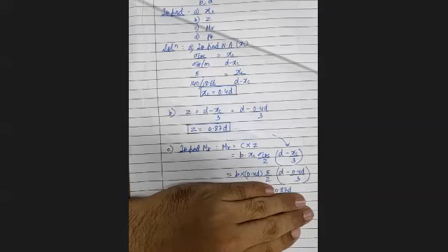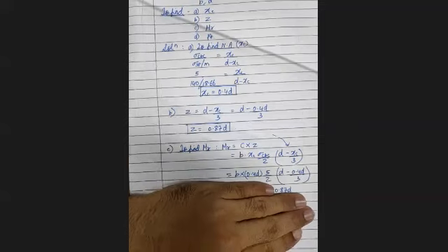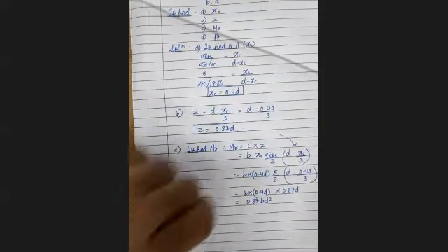Yes, Saurabhji. We have assumed it as a balanced section to find MR. Since you don't know the AST, so we are going to use MR is equal to C into Z. Is that clear? Okay, 0.87 BD square. Correct.